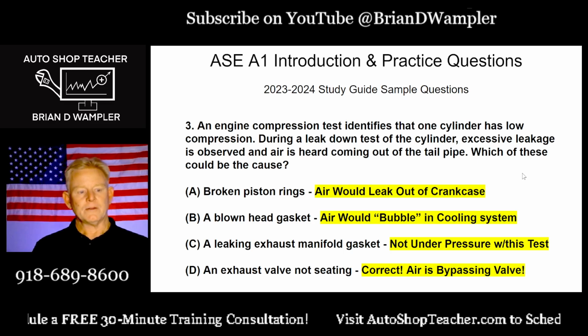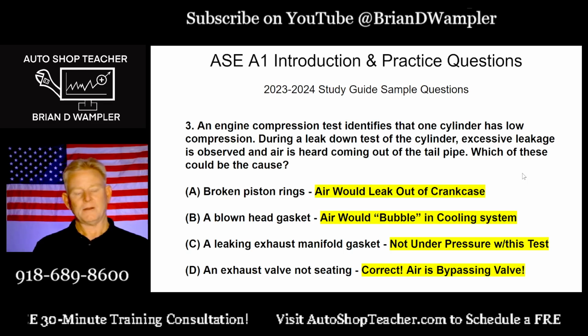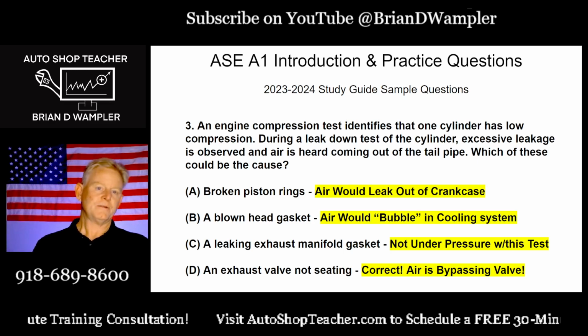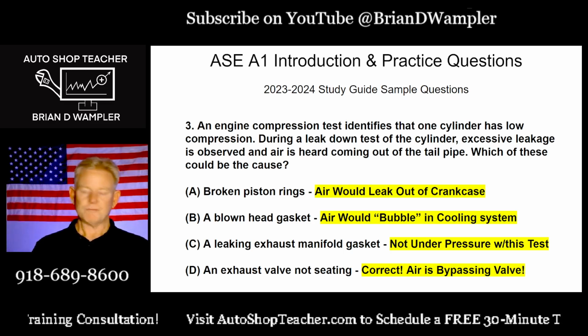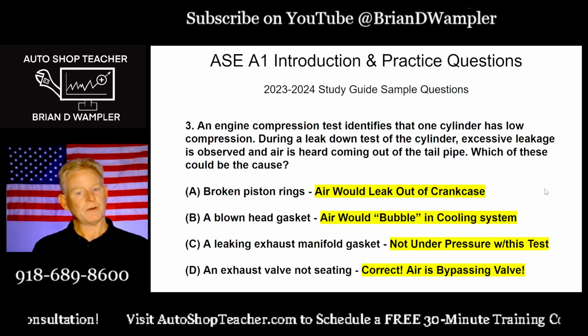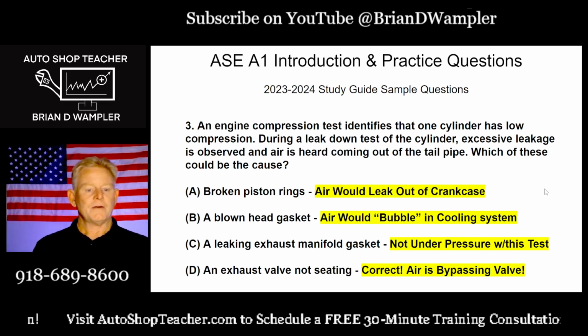Option C here, a leaking exhaust manifold gasket. Okay, we're talking about the gasket between where the exhaust manifold bolts to the side of the cylinder head. So it's not under pressure at all when we're doing this test. If it is, there's something really crazy going on. And then D, an exhaust valve not sealing.